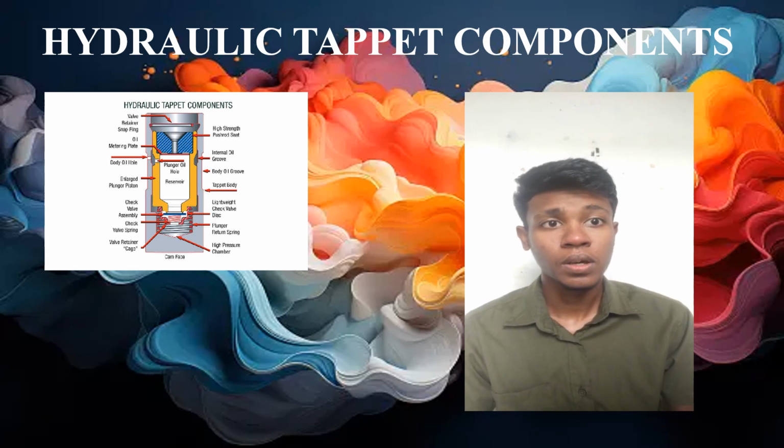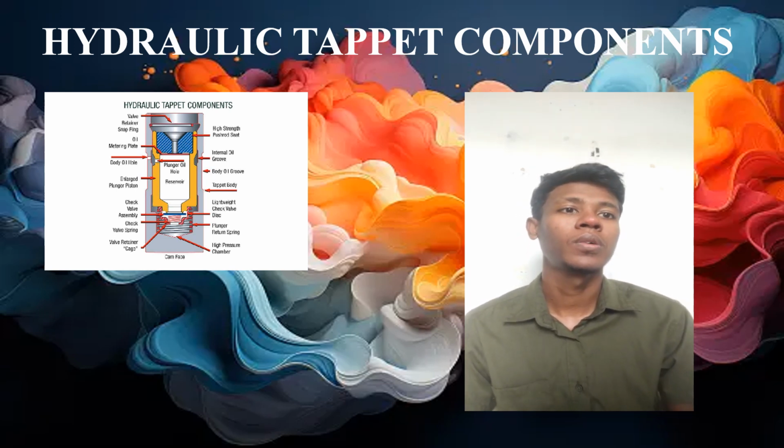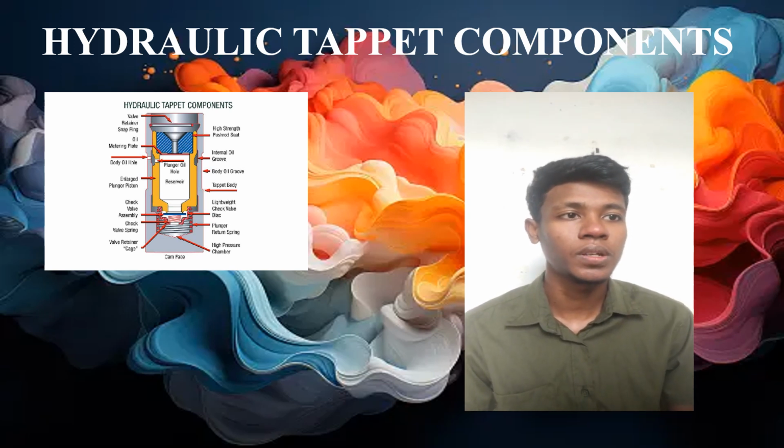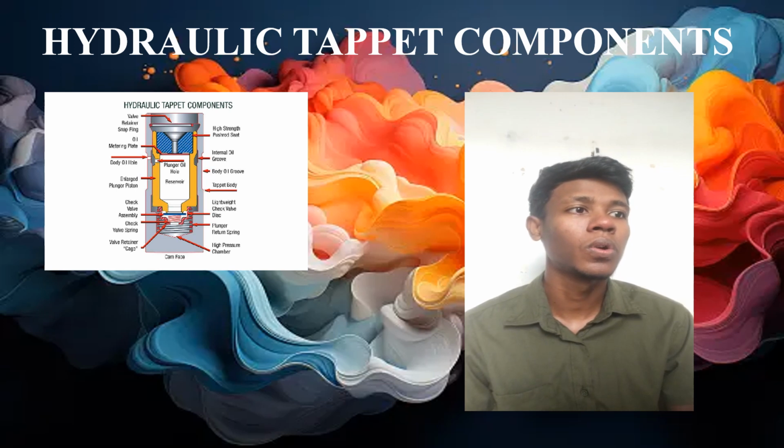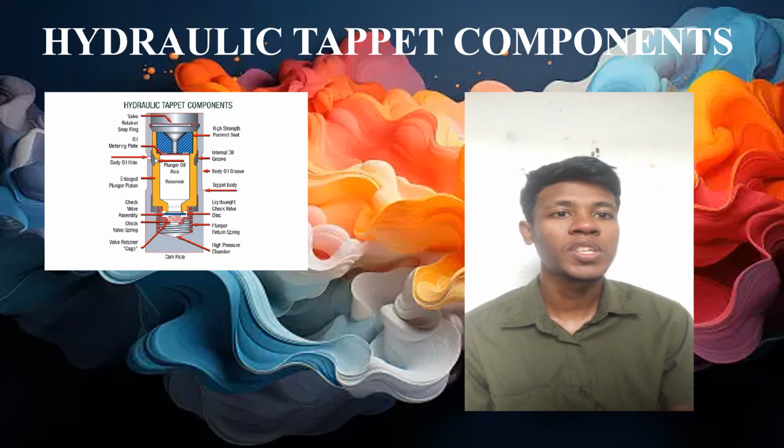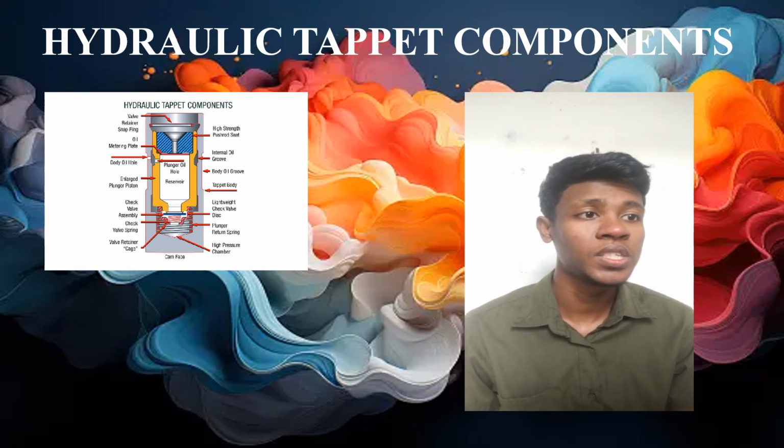The hydraulic valve lifter works by using a small piston and a hydraulic fluid chamber to take up any gaps in valve clearance. It is typically located between the camshaft and the engine valve.